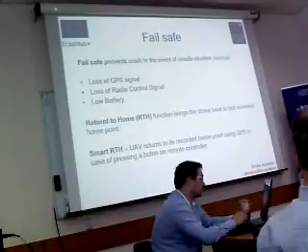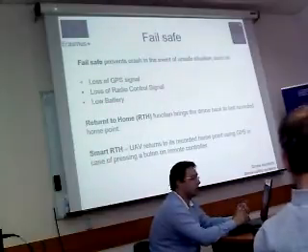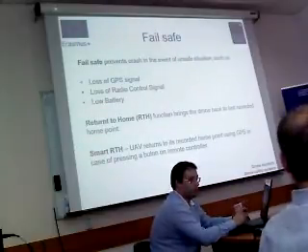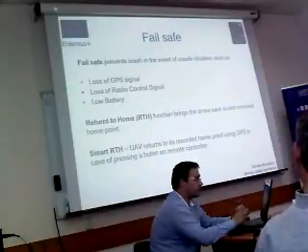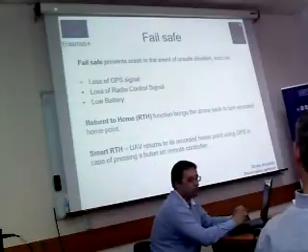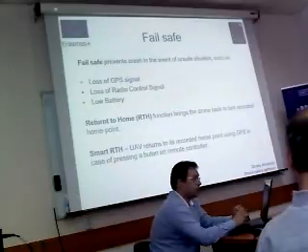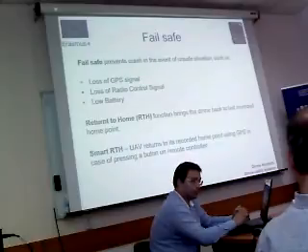So, for example, in case of loss of GPS signal, the UAV should attempt to reconnect. The UAV will hover for an established time. Once the established time has expired, the UAV will, for example, land on the spot. If the connection is reestablished, the UAV should immediately return to launch or evacuation.